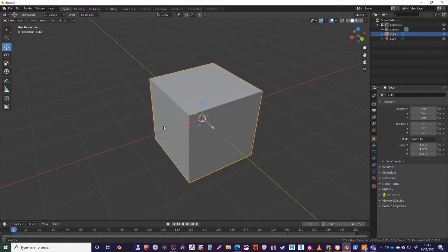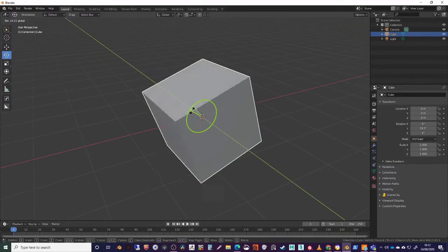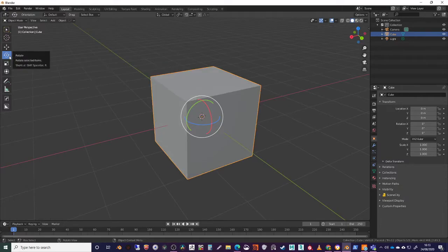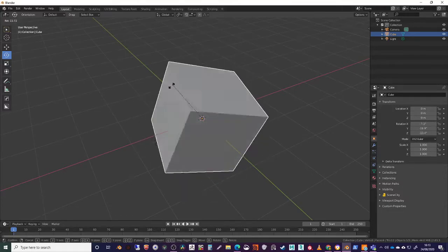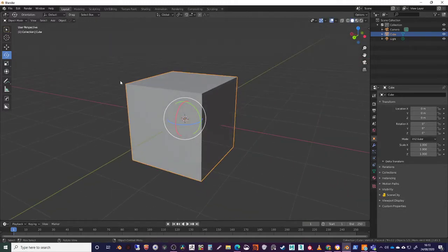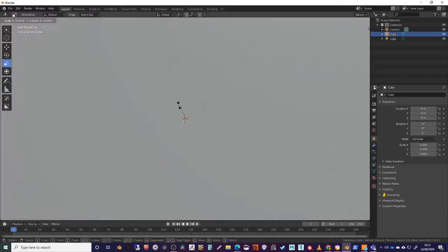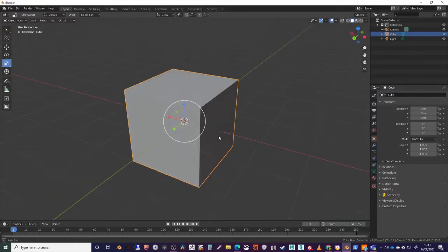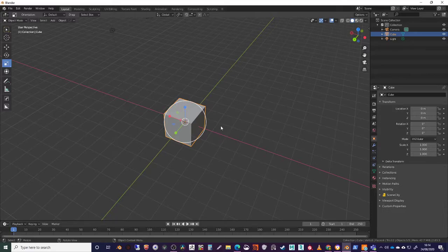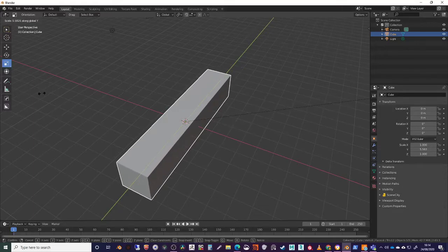So if you're just playing around with things, the same can be said for the rotate button as well. So there's a rotate button, and again the hotkey for this. If I just Control Z to undo, the hotkey as you look over it is R. So we can go R, and we've got the rotate, and it will rotate around the axis that we're actually working on. But if we press the right mouse button, we don't commit to that. And then S for scale. So if we press S for scale, we can scale up. And again, we can not commit. If we zoom out a little bit, it's contextualized, so it'll work better. So the further away we are, the easier it is to control. And it also works with the locking mechanism. So if I do S and Y, I'm only going to scale across the Y-axis. So that's pretty cool.